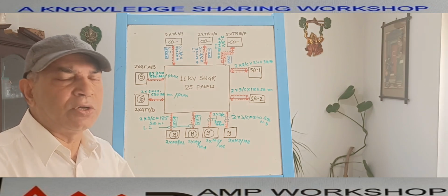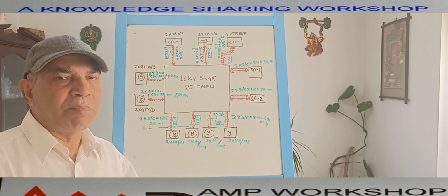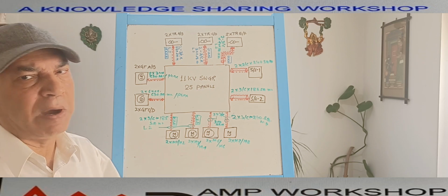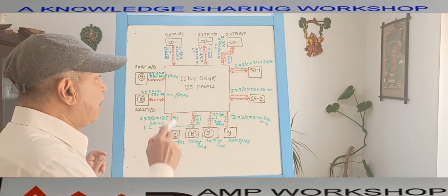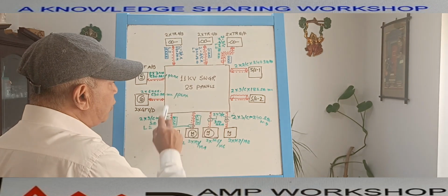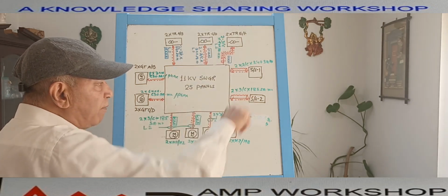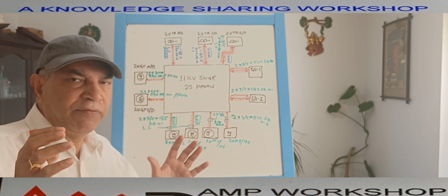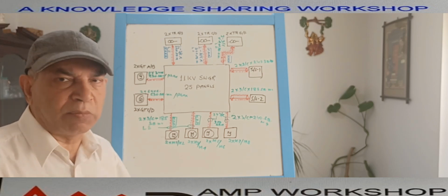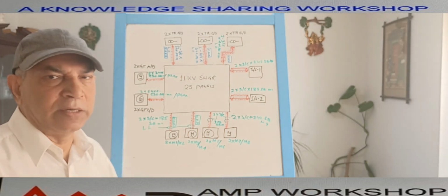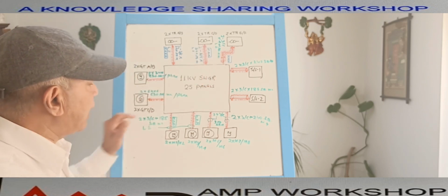Today's video will be discussing only the power cable block diagram, concentrating on the major power as well as CT-PT power, which is coming from the field to the switchgear. Here the switchgear is the mother equipment. I have shown the switchgear over here. This is the 11 kV switchgear, which consists of 25 panels. That means in the field there are a total of 25 or more cables, because if one equipment needs two cables, then the number of cables will be more than the panels, but a minimum of 25 cables will be in the field. So all the cables are coming ultimately to the switchgear.